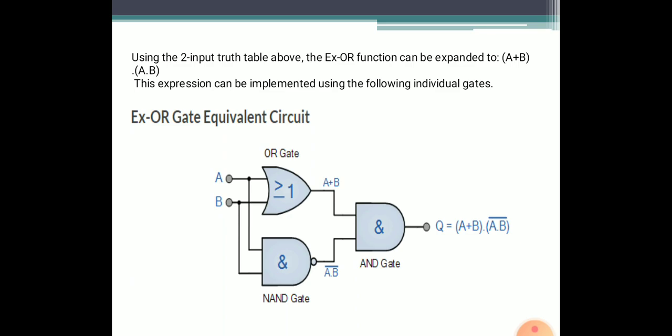The logic function implemented by a 2-input XOR gate is given as A or B, but not both, will give an output at Q. In general, an XOR gate will give an output value of logic 1 only when there are an odd number of ones on the inputs to the gate. If the two numbers are equal, the output is 0. An XOR function with more than 2 inputs is called an odd function or modulo 2 sum.